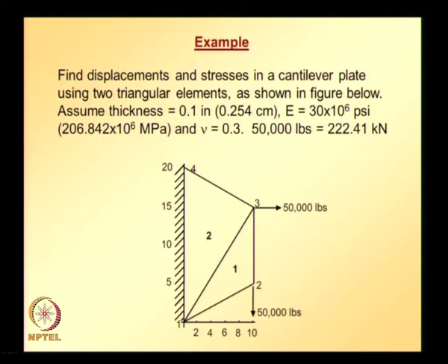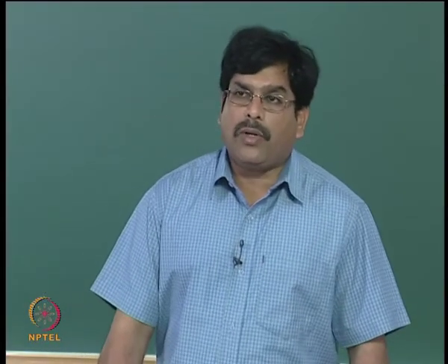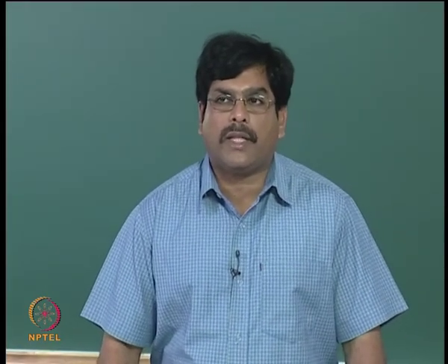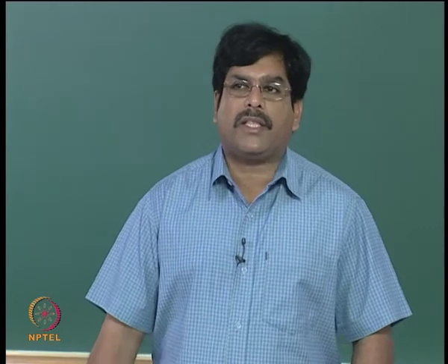and the figure is drawn in FPS units. So, whatever coordinate information that we get from the figure, please read it as inches corresponding to the nodal coordinates. The cantilever plate is discretized using 2 triangular elements and all the nodes are numbered, and the 2 triangular elements are also numbered. Element 1 comprises nodes 1, 2, 3 taken in counterclockwise direction.